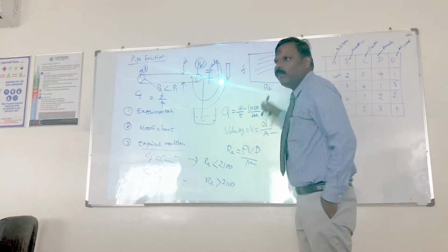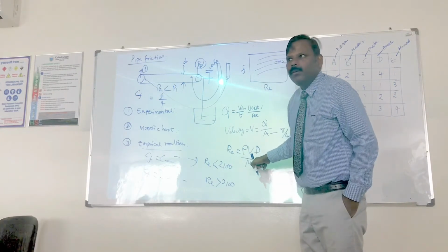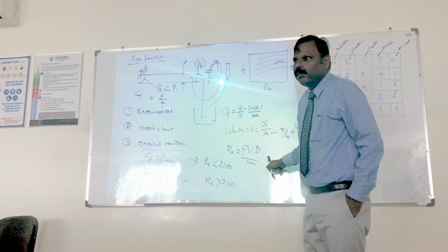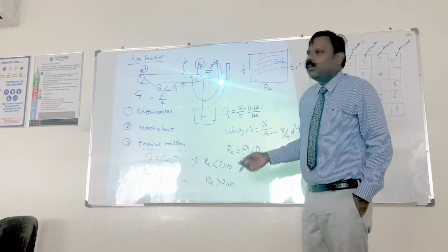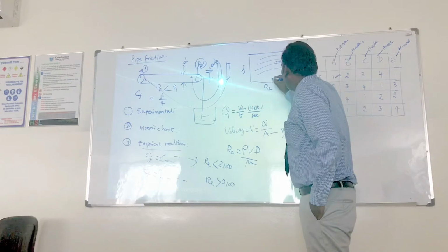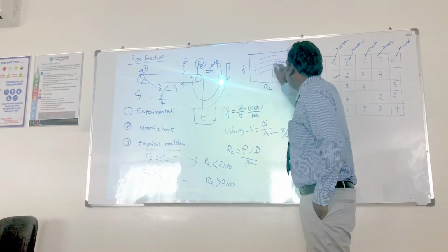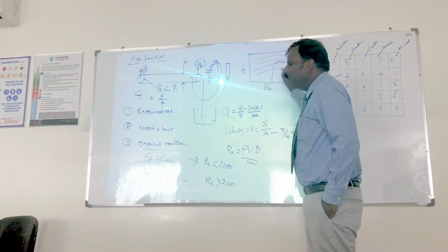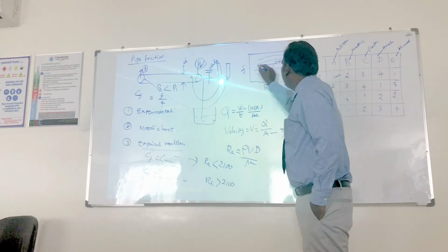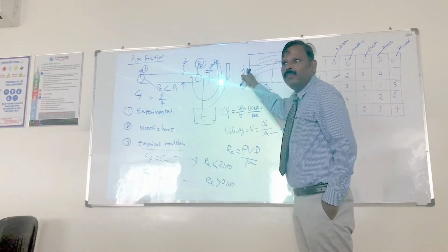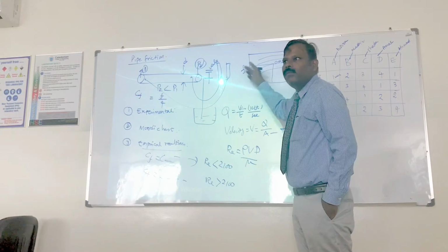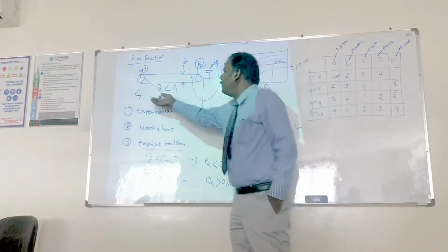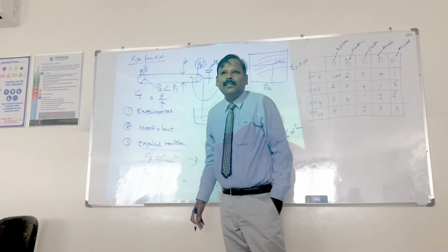Now what am I going to do? You have the Reynolds number value? Do you have a Reynolds number value? Okay. Draw a vertical line from this. This is my curve for the roughness value. Draw the vertical line, then draw the horizontal line. Can I get the F value? Yes. Finish. If I know the F, then CF is nothing but F by 4.